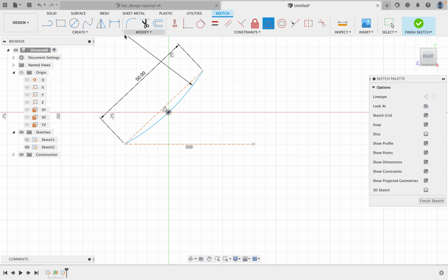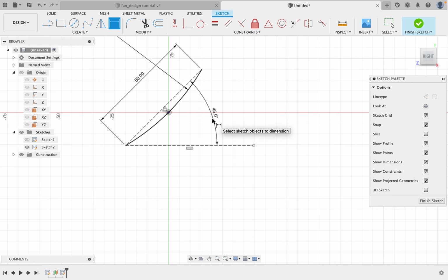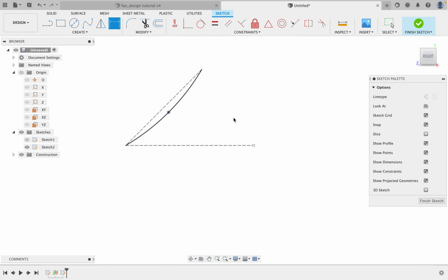Perfect. We're getting closer. Next, I'm going to use the sketch dimension to add an angle between here and this construction line that's here. Perfect. And then move your mouse out, then click. Here's the only change I want us to do, because in the last sketch we made it 80 degrees. Here we can do 45 degrees. Perfect. Our geometry is all constrained now because it's all black in color, so I can right click OK and then finish my sketch. Perfect.